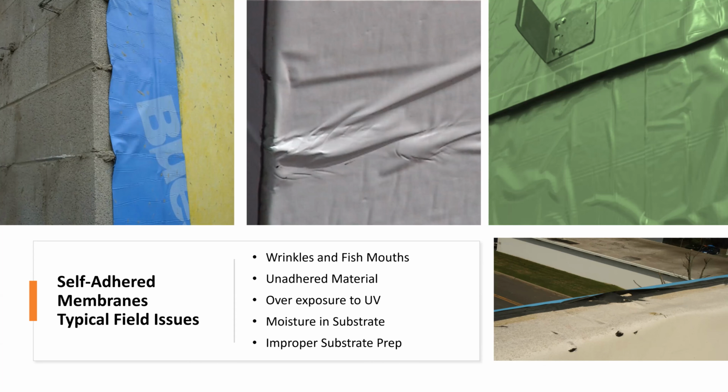Okay, so again, that moisture starts to dry out of that substrate. It starts to debond the material. So the installer's like, well, no, I rolled it and hey, I checked it for moisture, was good. Option number 3, if they don't let the primer set up enough time and they put it over a fresh primer that hasn't cured, again, it will not stick properly.